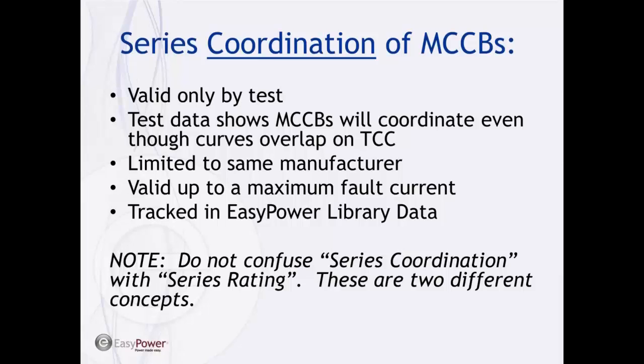I have a question about the recommended coordination time between breakers. Actually, for low voltage devices, the time current curve that the manufacturer provides for the breaker includes all of the tolerances and the operating time and the fault clearing time. So as long as you can see daylight between the curves, between two molded case breakers, they will coordinate. You don't need to add any additional separation. That's not necessarily true for all devices, but for molded case breakers that we're talking about today, all you need is daylight between the two devices. Unfortunately, because of the instantaneous trips, there's not too many of them where you're going to see daylight all the way along.